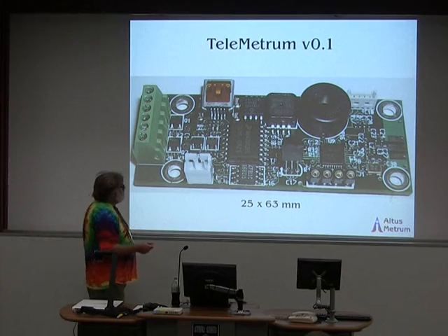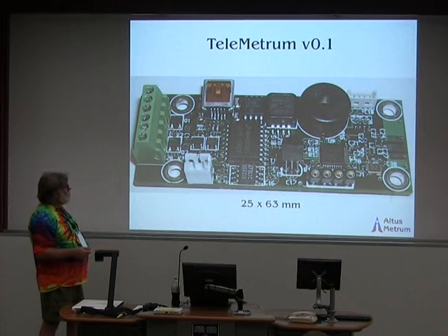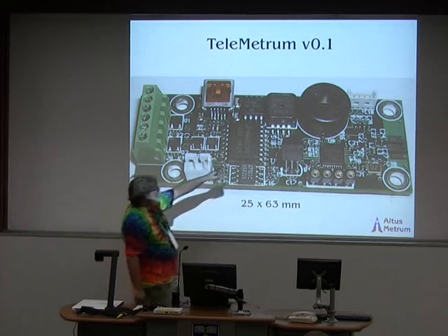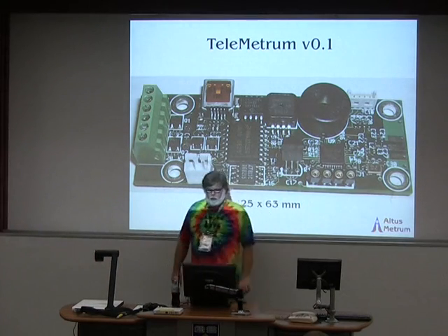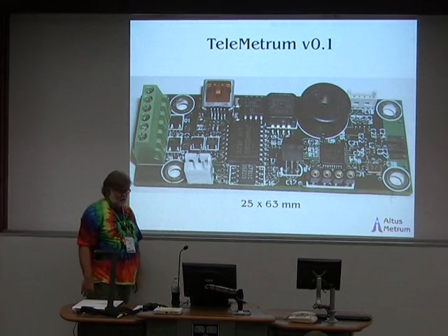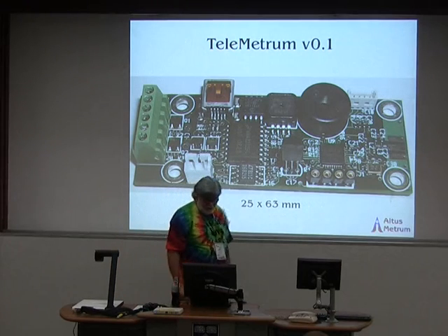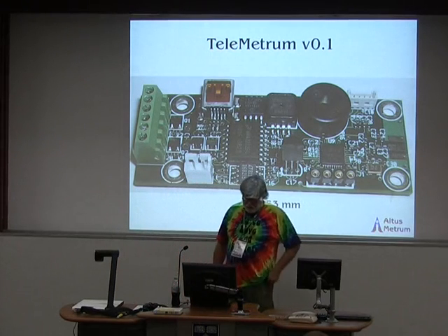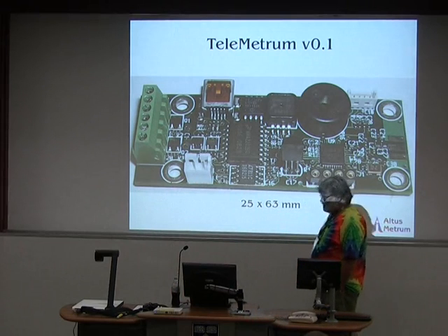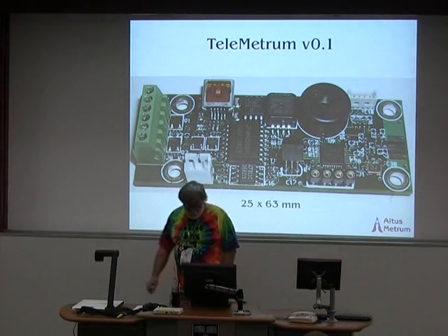So it ended up being a really interesting design, and it actually all worked, which was just amazing. The white connector up in the corner, a little 4-pin connector, is the other serial port. The 4th pin is so that we've got power, ground, transmit, and receive. That ended up being handy because a lot of the little SparkFun GPS boards have power in it. And as you can see, that's 2.5 inches by an inch.